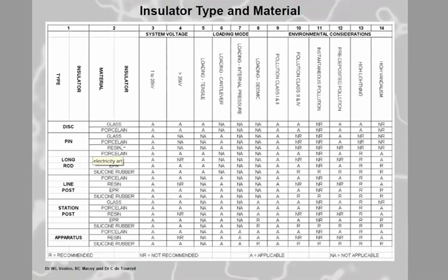That reduces its wet flashover voltage by about 20%, okay? You will find that the material, once it's subjected to high humidity and localized arcing, will break down quite readily, and it will be due to hydrolysis. So there's an inherent problem. It's not to say you can't use it, but you will use, for instance, cycloaliphatic at 38 millimeters per kV, where you would use porcelain at 31.